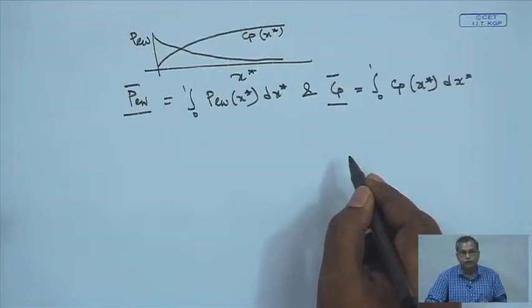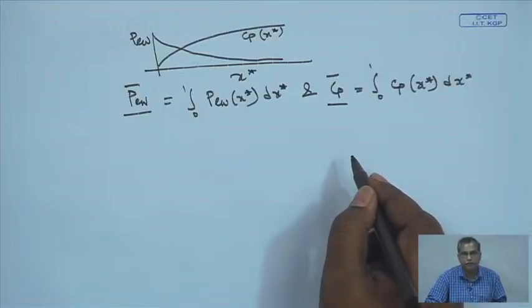So, for a well defined system where we know the solute diffusivity and the geometry of the system perfectly, everything is known, then this osmotic pressure control filtration model can be utilized to get the system performance. Now, let us go a little bit ahead and look into the mass transfer coefficient, and see how the estimation of the mass transfer coefficient will help us in reducing the rigor of calculation further.